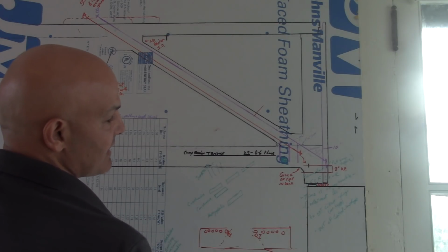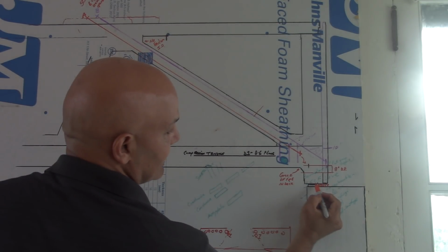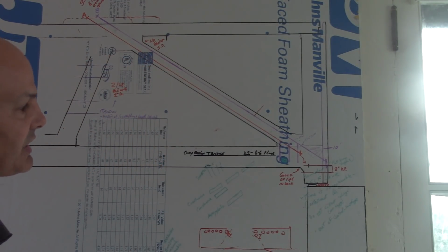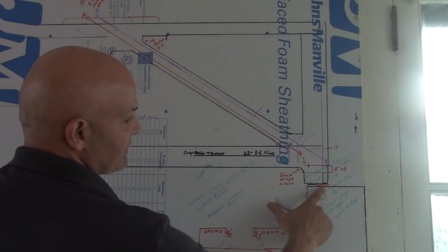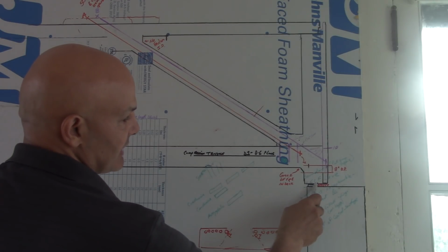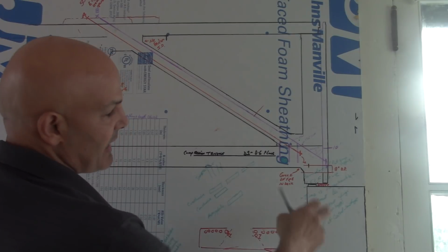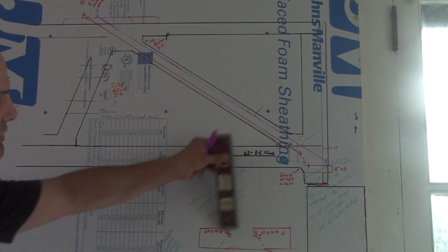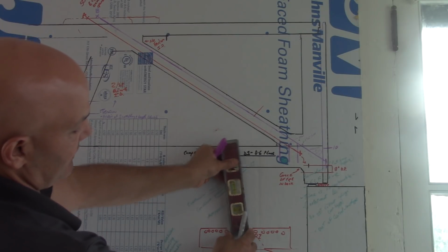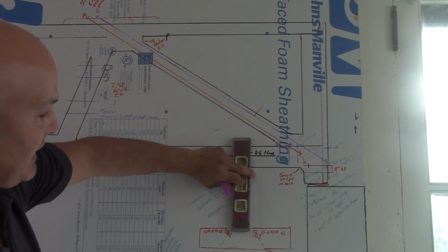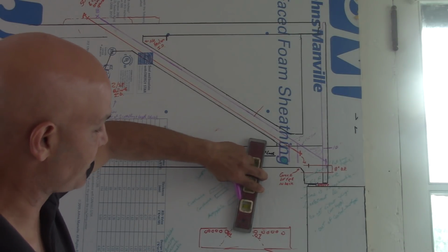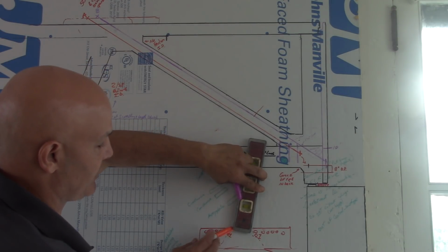I have to know that this is in plane. Say I didn't look at the shims, 2.5 inches, and then I see that they're bigger than that. So let's call it 6-inch shims, and I see a 4-inch drop here. That means the back of this dropped 2 inches. That means the shear on the bottom of this rotated this column like this. Watch this. And this is the way I see it. Well, I see it actually this way. We see it this way and a shift over, as I showed you in the previous videos, at the base.